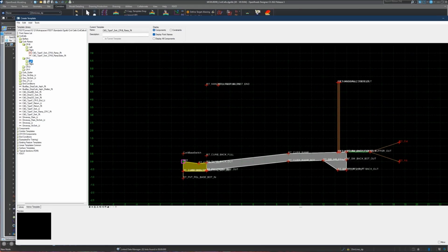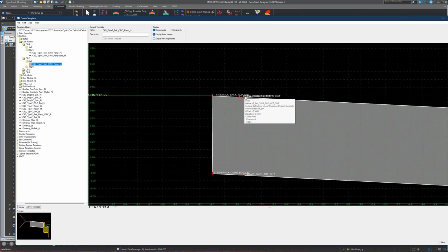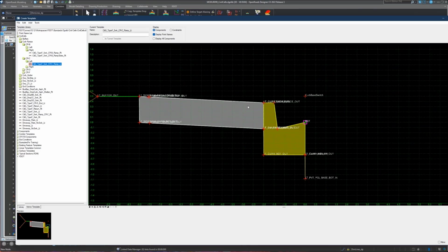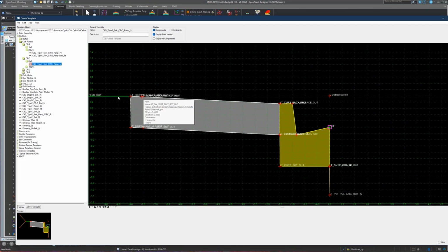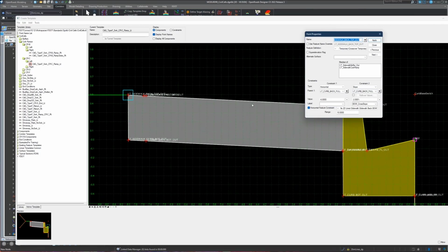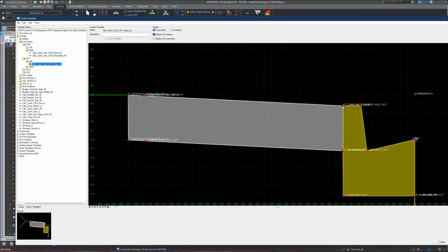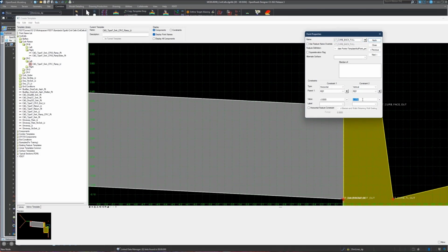So let's look at CRC, look at left. And this one, I've got to build in this header curb. It's pretty similar. I've still got that curb back out full because I want that point right there to always be 2% up. And then I'm just going to move the curb back out full up out of the way a second.